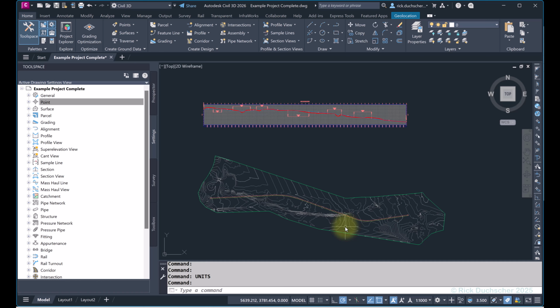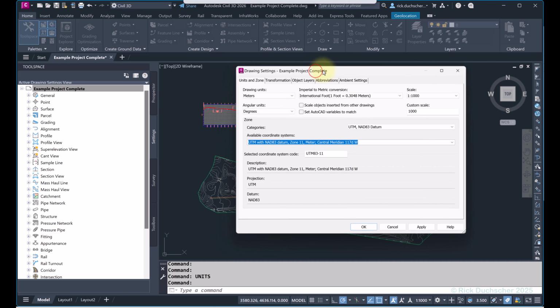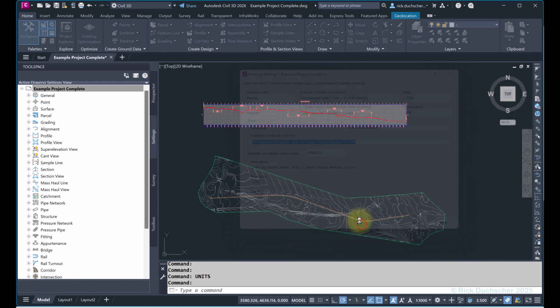So make sure you go into those edit drawing settings and set that up. That's really important that you go through that and check that out first. Now this also is going to be saved in the drawing template. So that's another important thing here where we're talking about AutoCAD Civil 3D: we want to use the right template, because you can have all this stuff pre-loaded into the template file.